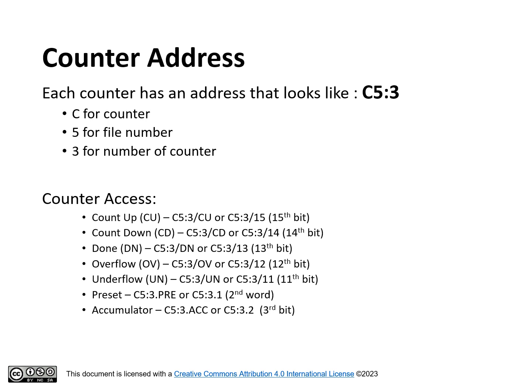Done, DN, C5:3/DN, or C5:3/13 on the 13th bit. Overflow, OV, C5:3/OV, or C5:3/12 on the 12th bit. Underflow, UN, C5:3/UN, or C5:3/11 on the 11th bit.